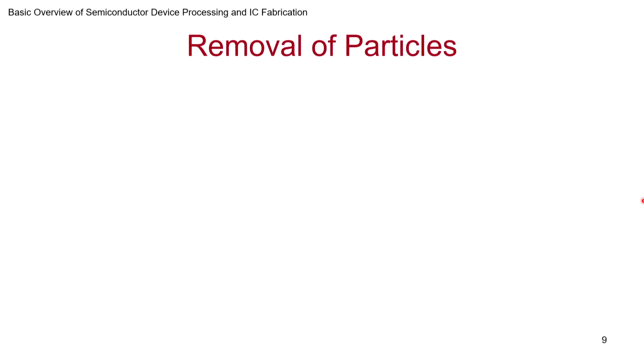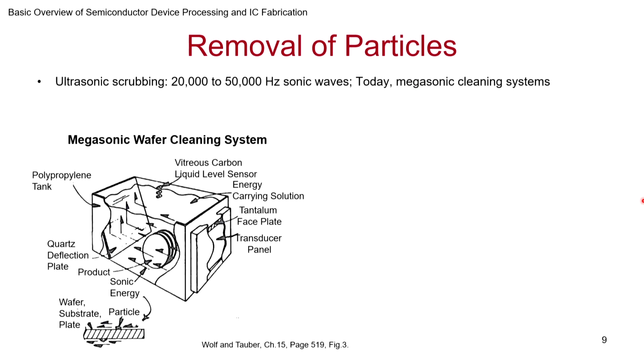How do you remove particles? Over time, a lot of interesting ideas have developed, and some of them have come for many decades. One of the things that is very popular, and you may even find it in your labs if you are doing processing, is to use an ultrasonicator. So ultrasonic scrubbing, as it is called: at a very high frequency, sonic waves are sent into the solvent in which the wafer and other things are dipped.